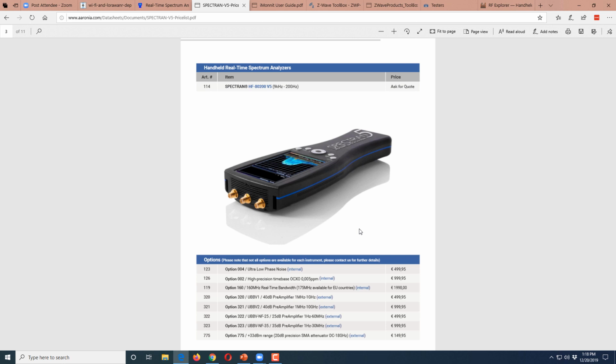Now, would I want this tool if every day I was troubleshooting these different types of networks running in 900 megahertz, 800, 400? Yes, I'd want this tool. And because it sweeps the entire spectrum, and it is a spectrum analyzer, meaning that it doesn't matter if there are new versions of the protocol, as long as they still work somewhere from 20 to 20, right? So somewhere up to 20 gigahertz, as long as they work in that space, this spectrum analyzer will show me the RF, because that's what it shows me is RF. So this is a definite power tool and one you could get.